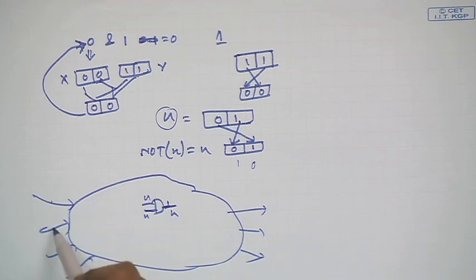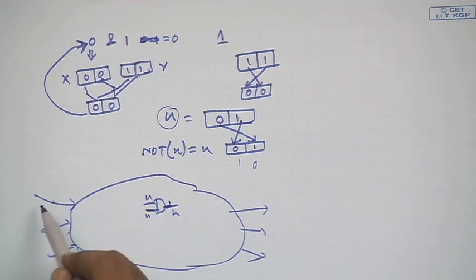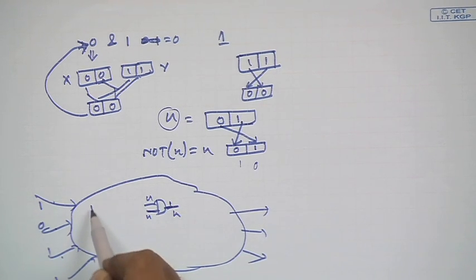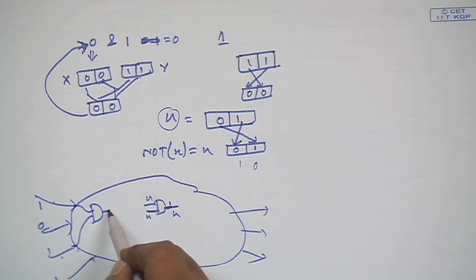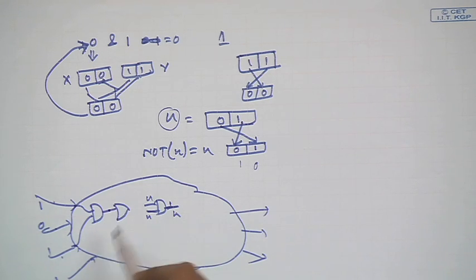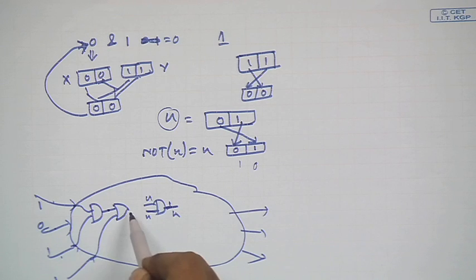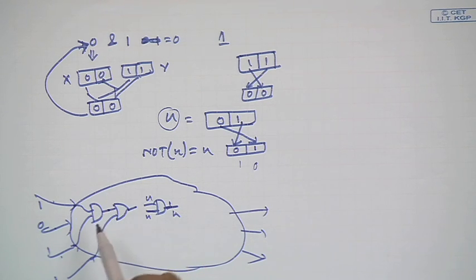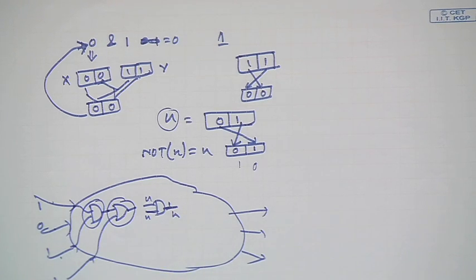But since these primary inputs are there, the test vector that we have has specified the values of these primary inputs. So, if I have a gate here which is fed from these primary inputs only, then I can simulate this gate first. Now, after that, if this gate feeds another gate like this, then I can simulate this gate. So there is an order in which I should do the simulation. I should first simulate this gate, then this gate, and then proceed level by level. This is known as a topological ordering of gates, or topological ordering of nodes in the circuit.